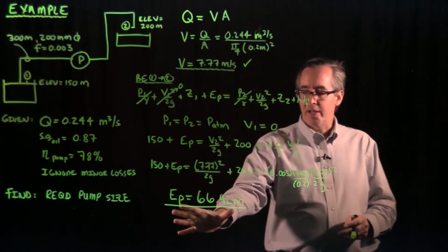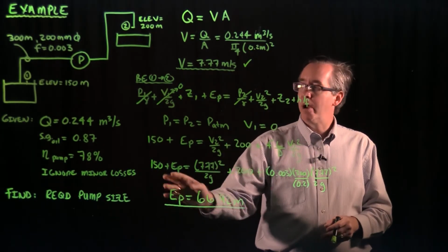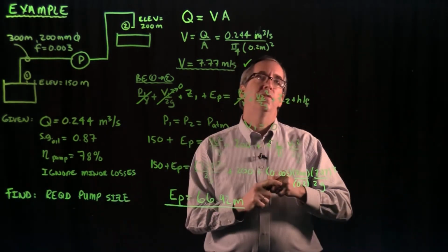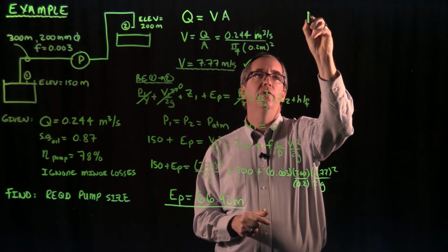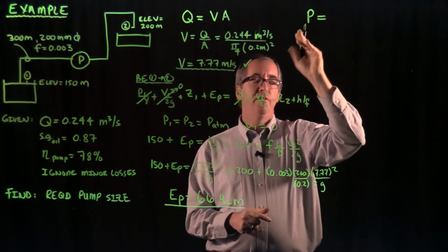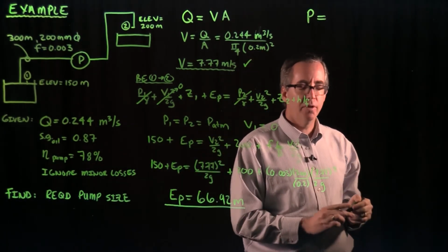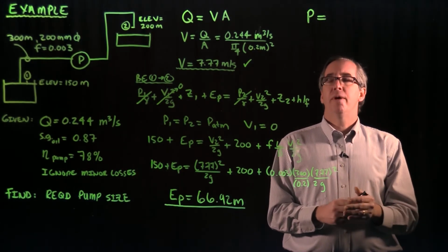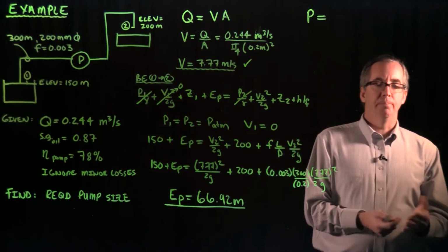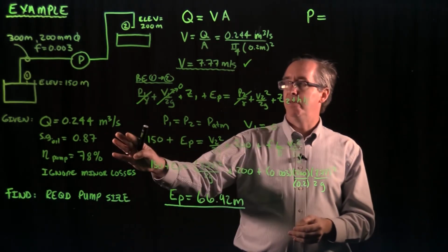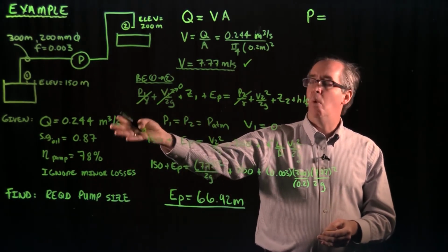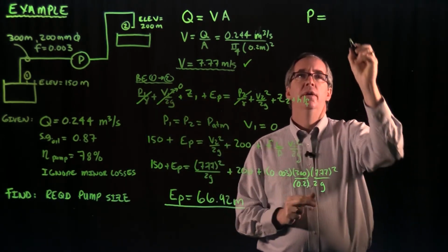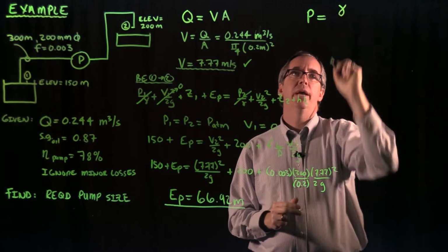Now, this is great. We've got the pump head, but what we're actually looking for in this problem is to size the pump, so we have one more step. Now, if we look at the power equation, and if you ever get to the point where you forget what the equation is, you can reason this out. In the numerator, we have to think to ourselves, it matters what we're pumping. It matters, for example, if this was oil or if it was water. Whatever it might be matters in terms of the weight of the fluid, so we have to consider the specific weight.